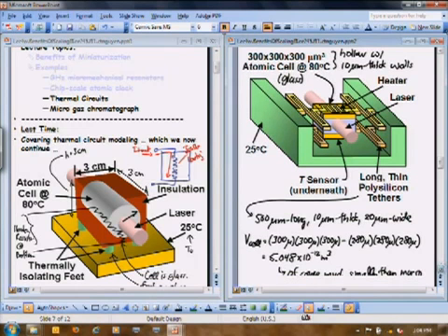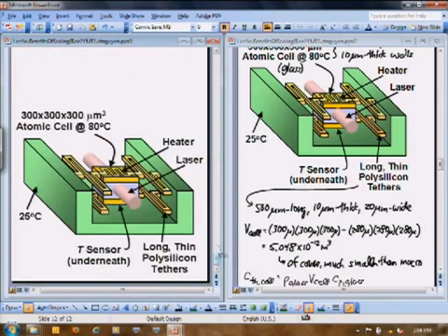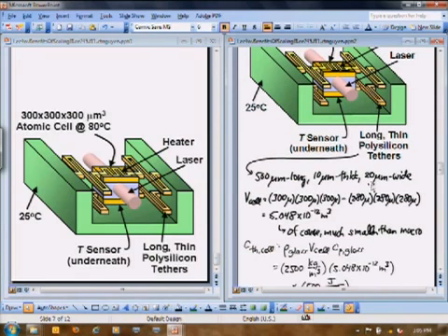I can keep that there. But right, if my supports are 500 microns long, maybe 10 microns thick, 20 microns wide, and if my cell is 300 by 300 by 300 minus what I'm calling a box of open, a hollow box, right? So minus that hollow portion there. We're now looking at a volume of 5 times 10 to the minus 12 cubic meters. Okay, extremely small compared to that macroscopic thing.